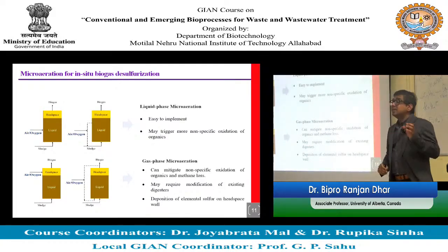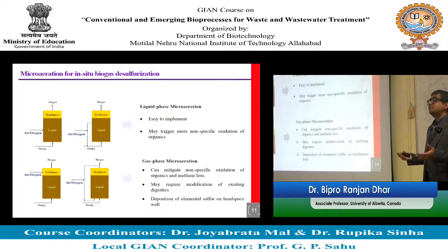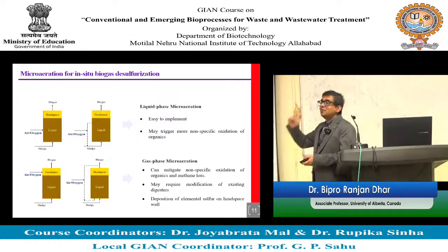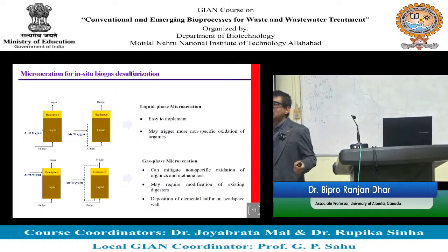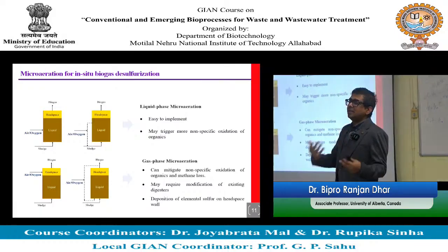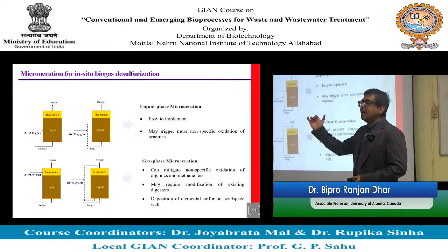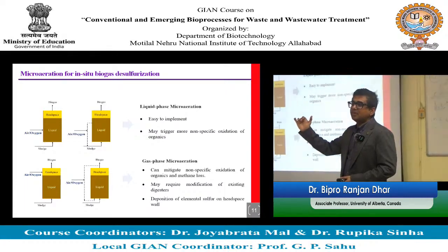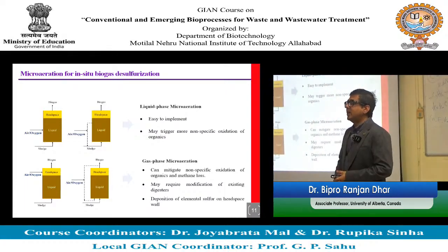Another challenge is that operators are sometimes scared of providing air in the headspace, because methane is flammable, right. You could have an explosion if something happens. Let's say somehow your process control system fails and you have very high oxygen injection in the process, it can cause a fire.